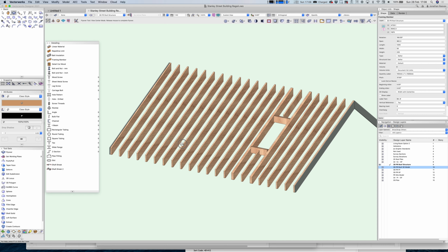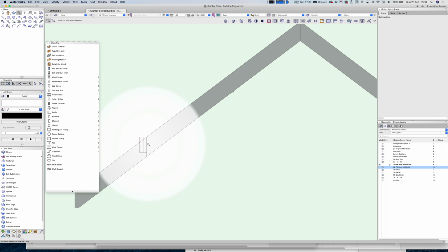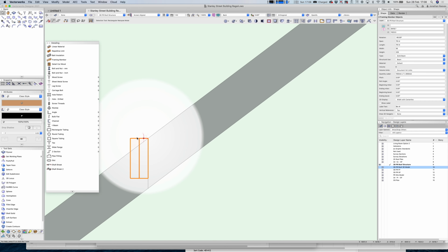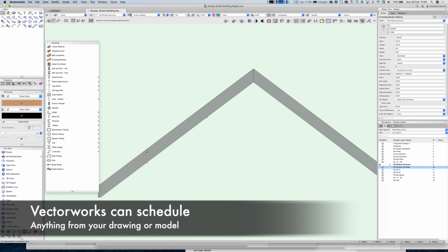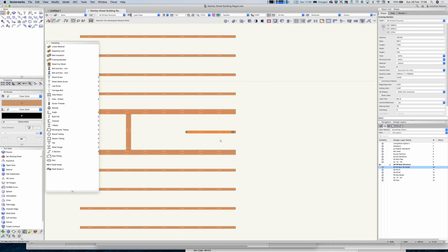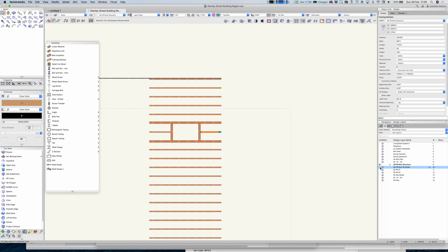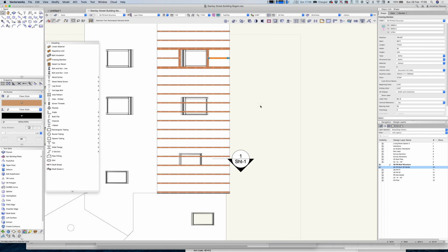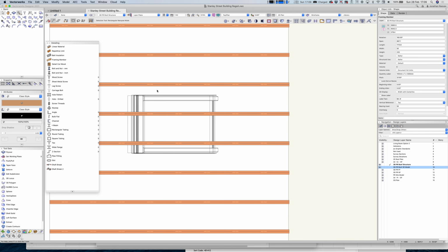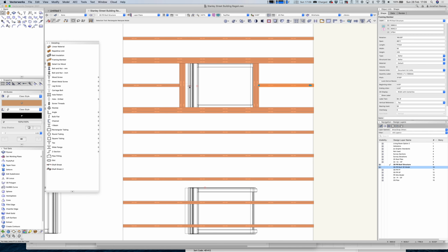It's also really helpful in terms of costing, just to be able to see how much timber is required for the roof. A bit later on when I'm ready, I could actually do a spreadsheet, a worksheet, where I could quantify all the individual framing members and get almost a cost estimate if I knew the rates per linear metre. So I find this process very useful to reassure myself on the design that everything's going to work. I can show the engineer what my design intentions are, and the engineer can give advice on things like the rafter sizing and the structural calculations for the beam sizing and so on.